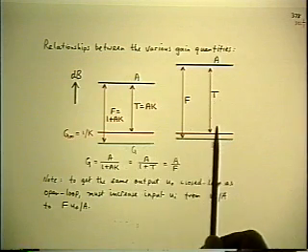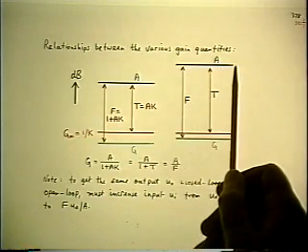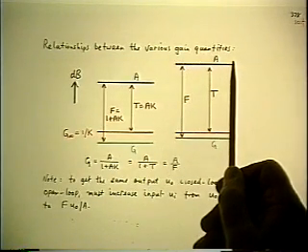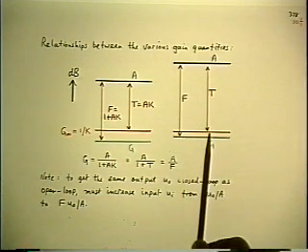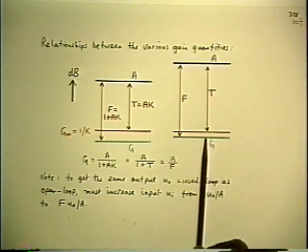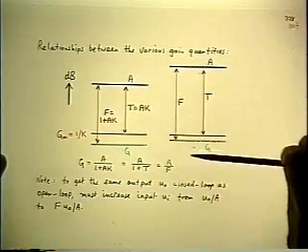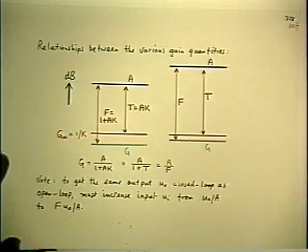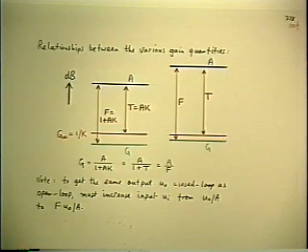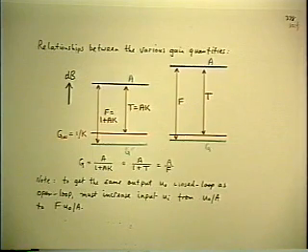And the other picture is what happens if you have the same specification, but you started out with a forward amplifier that had a bigger value of gain A. Both the T and the F get bigger, and the D gets closer to 1. And ultimately, if the A went to infinity off the picture, D would go to 1 and G would approach the G infinity. So the purpose of this is to give you a little physical intuition as to the relationships between these quantities.